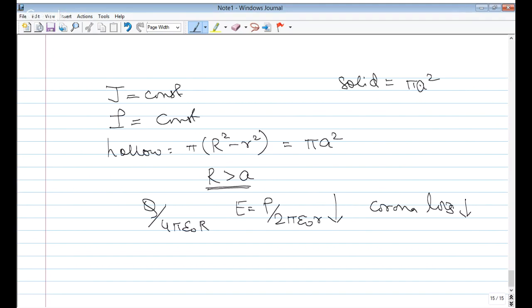The next is from Rupesh Kumar. A unity feedback system has open loop transfer function 25 upon s plus 8. Now a derivative component having a transfer function s by 10 is introduced. What shall be the damping factor? So G(s) is basically 25 upon s into s plus 8.